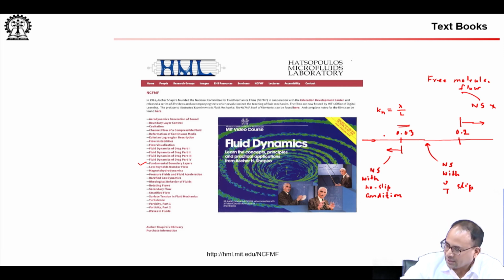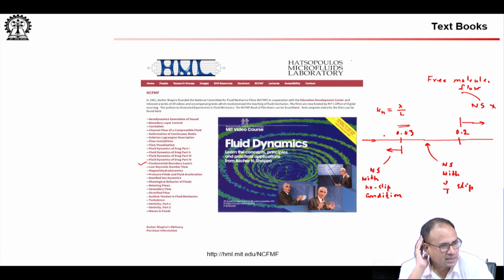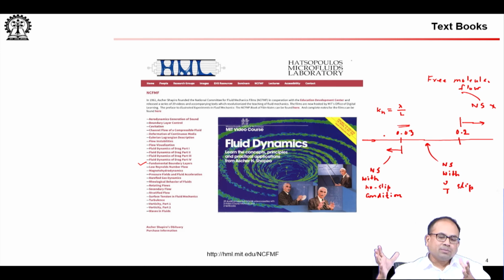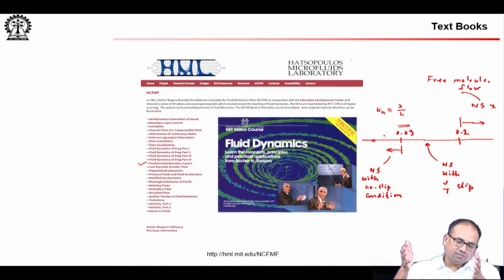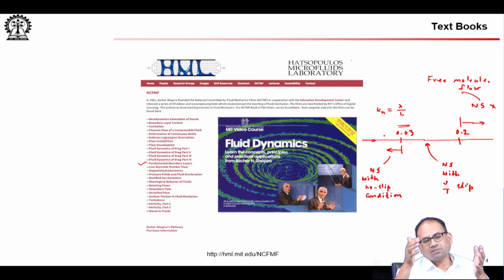In hypersonics, you talk about the constant dynamic pressure trajectory of vehicles, and you will see that your vehicle cannot fly if you fly below a certain dynamic pressure; your engines will not be able to produce enough thrust, and your lifting surfaces will not be able to produce enough lift.